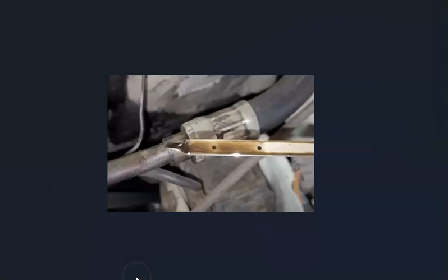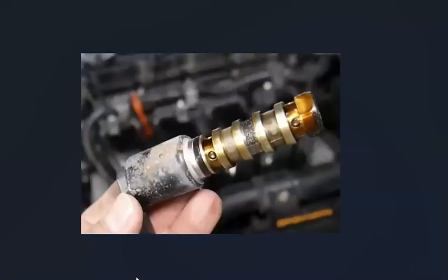The first thing to do is be sure that your oil is at the right level and that the oil doesn't look really super dirty, because like I said, this can clog up the variable valve timing and cause issues. There are also going to be these variable valve timing solenoids. Usually if these go bad, you're going to get another code, but you can go through and test them and be sure that the wiring's good and different things like this.